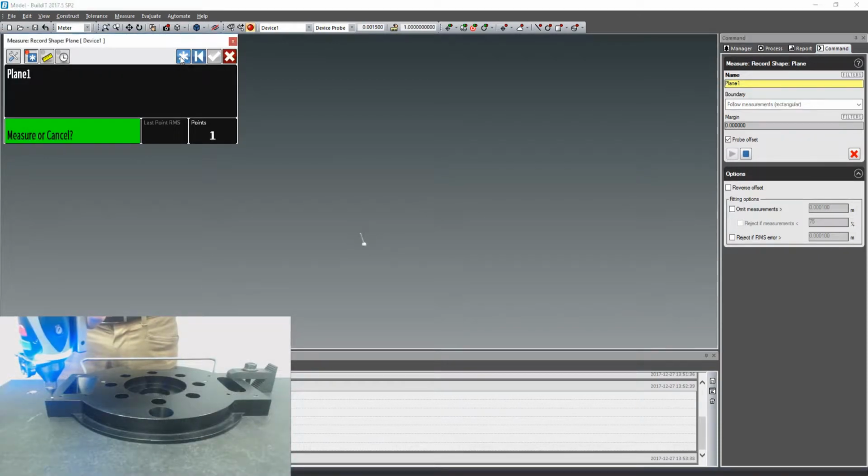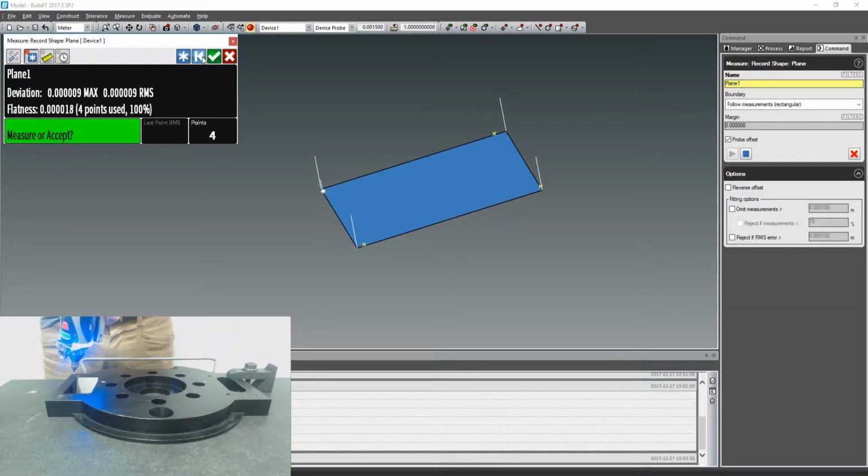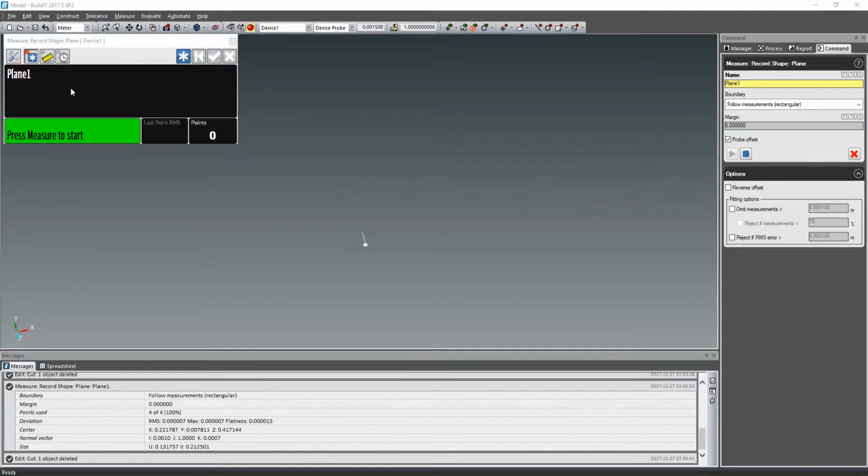Simply press your probe or SMR on the surface you want to analyze and record key points. In button trigger mode, click Measure to record a point. At any point before accepting the measurements, you can click Discard Last to remove the last recorded point. Once you acquired all the desired points, click Accept. You can also use the buttons located on your device.